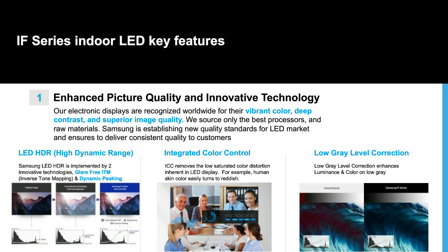Regarding a 1.5 millimeter pitch, standard luminance is 800 nits. When we implement HDR, we can increase that to 1600 nits. HDR is capable of producing a brighter luminance due to shifting the power required to light the diodes dynamically following the content. Therefore, if there's a black image, the diodes are not lit, and that energy is then utilized for the diodes that are lit, increasing the luminance by 2 times.